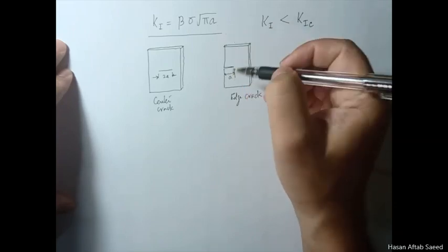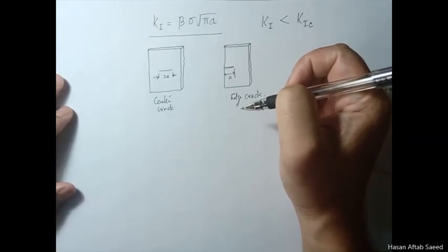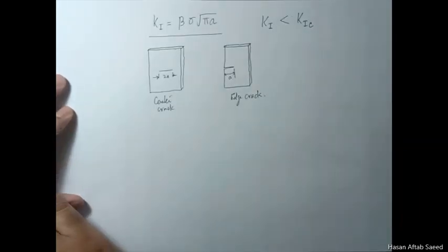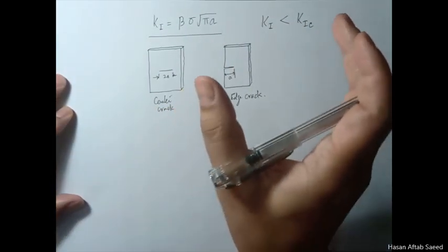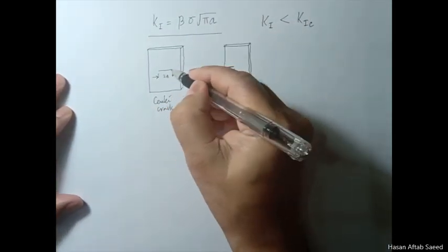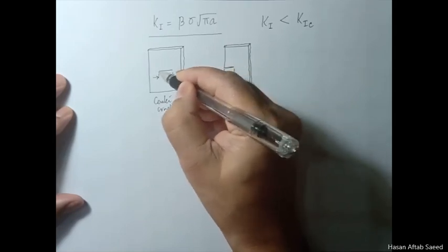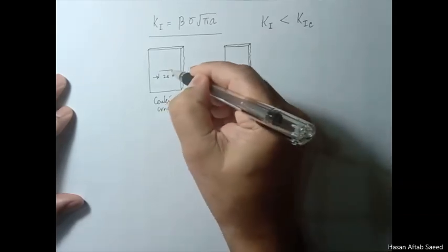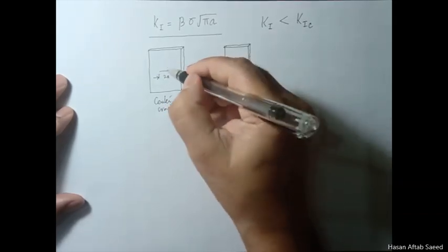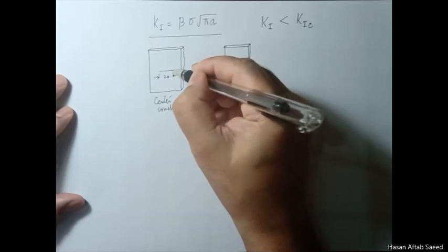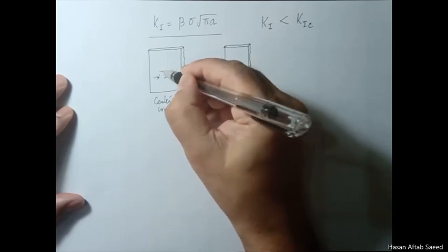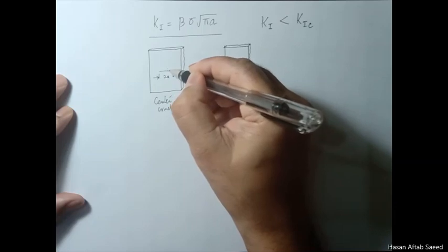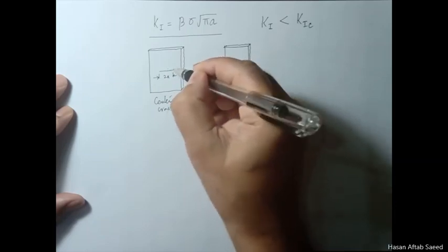In this way, maybe it is best to think of the crack length as the crack length per crack tip, because this has two crack tips. It has a tendency to increase in both directions, while this can only increase in one direction. So you can think of it like this: half the crack length belongs to this edge, half of the crack length belongs to this edge. And so for each crack tip which actually progresses, you can take half the crack length.